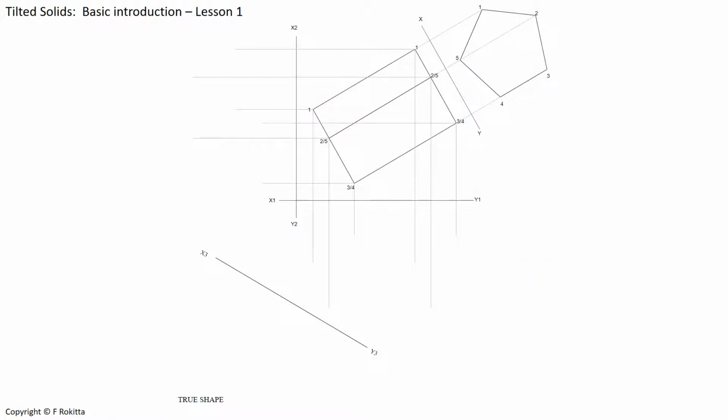Once you have done the projection lines from the front view to the top view, it might save time later on if you use the same principle now to project from your front view the construction lines of each of the corners of your prism towards the right view. And that will just help us with our measuring when we get to the right view later on in the tutorial.